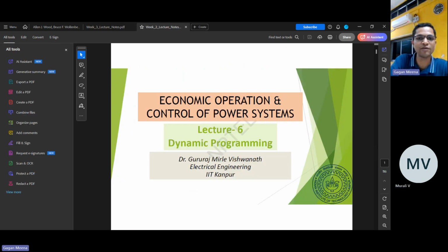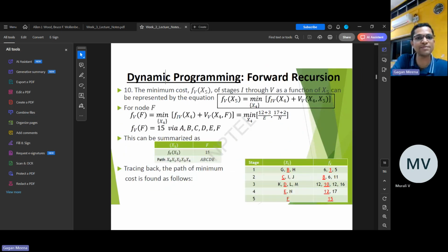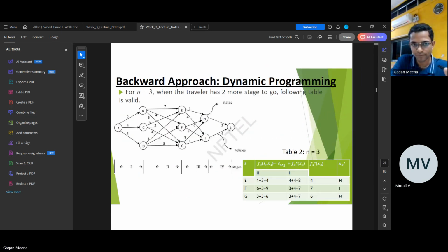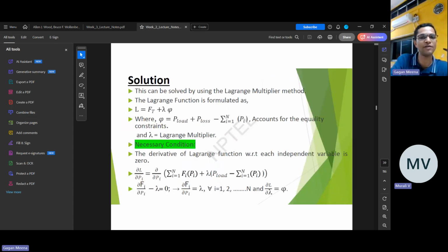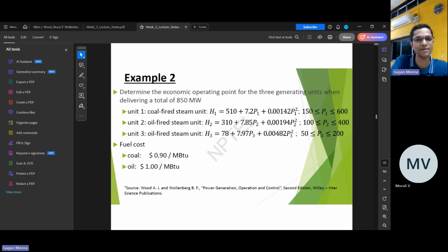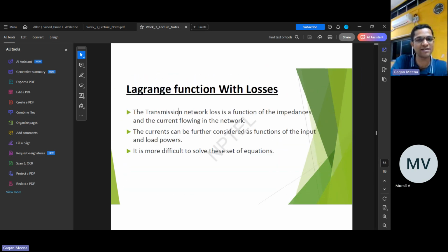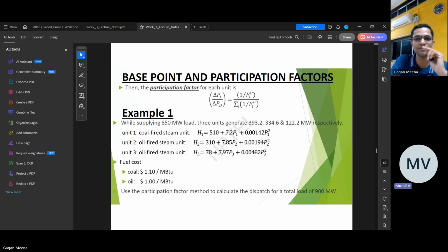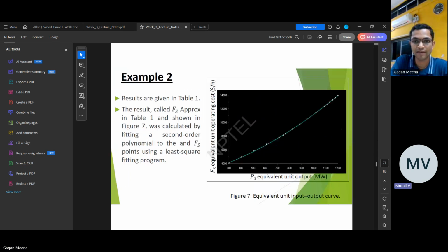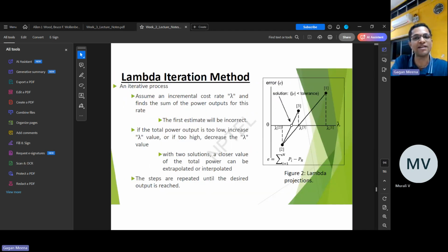So directly, if you do it with matrices, you take the incidence matrix A. Then you take the diagonal matrix BD, only the magnitude, not the imaginary part. The diagonal values of BD are 1 by X. It's a diagonal matrix. When you neglect the imaginary part, then there is no problem. So it is better to do that directly.